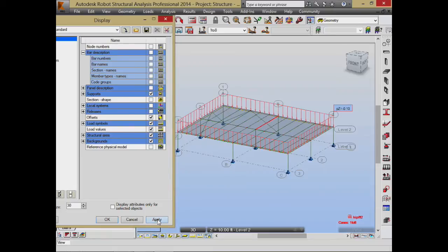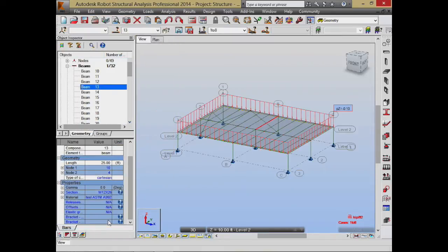What I can do now is, in addition to just showing the loads, I can do a preliminary analysis on this to really understand what the deflections would look like, and what the shear and bending moment would look like based on the load that's in there right now. So it looks like it's the dead load, something at minus 100 right now. I believe that's what we assigned as the dead load to this. Dead load, live load. They actually are both in there. It's showing me different loads for different cases. I can change the load.